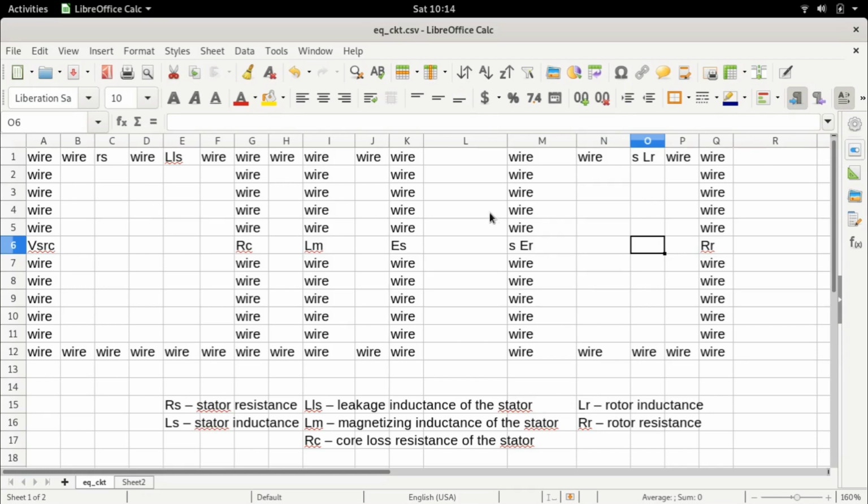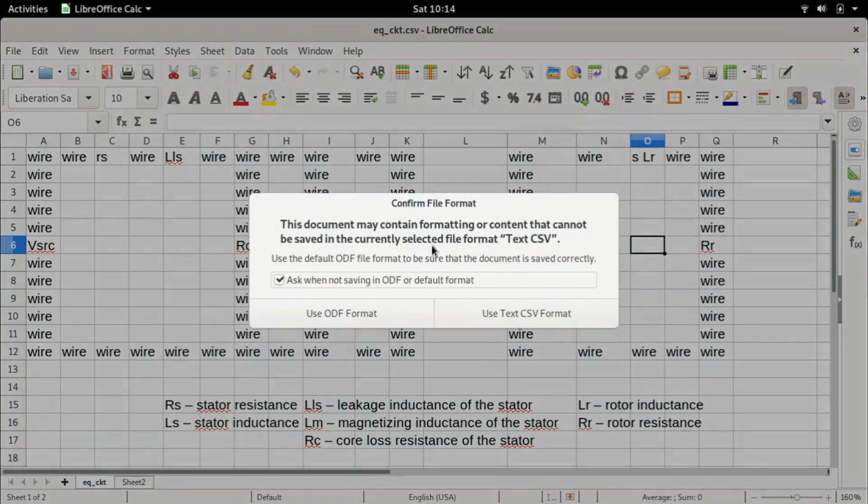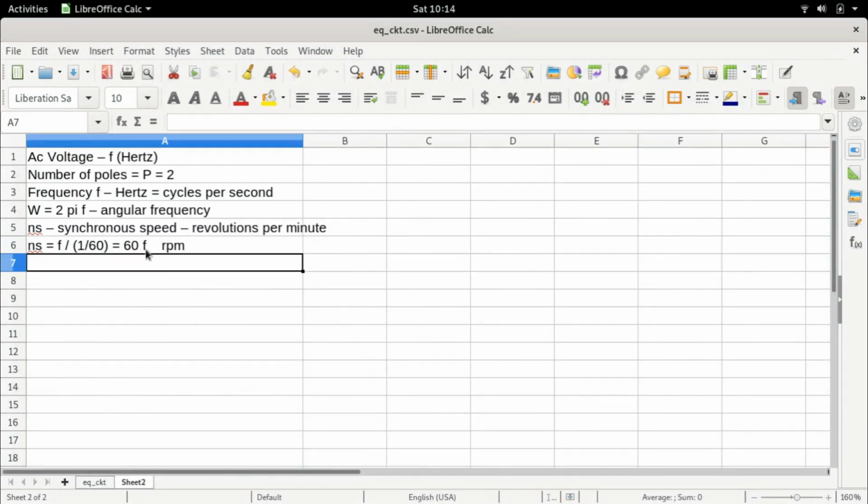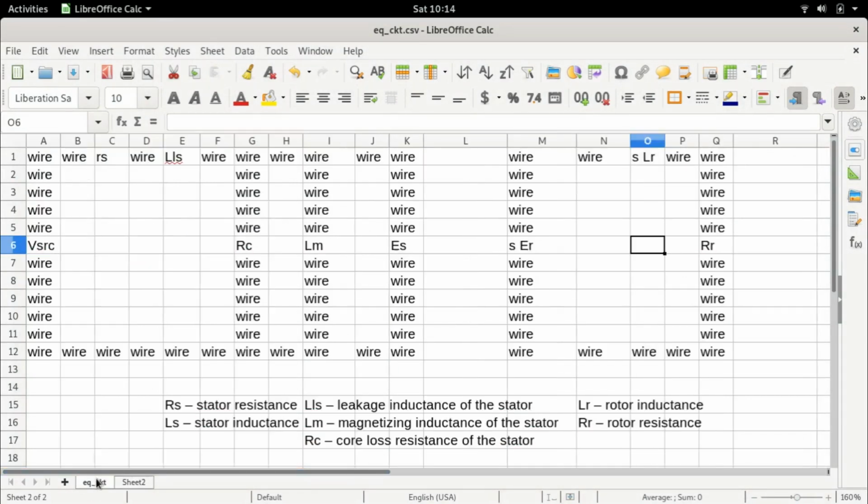Now, again, I'm going to stop here because the lecture is getting pretty long. The idea was to introduce this concept of the synchronous speed. We will talk about this again in the next lecture, where I'm going to elaborate about how not only does this entire rotor circuit have a lower frequency, but even the magnitude of this rotor induced EMF is much lower than what would be expected. It is multiplied by the slip S.